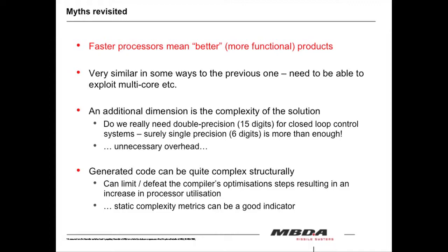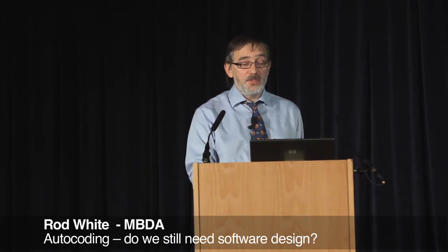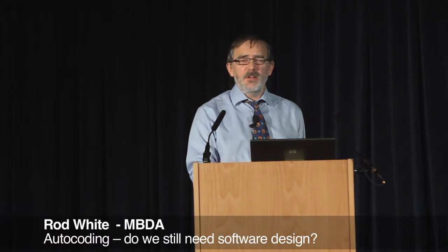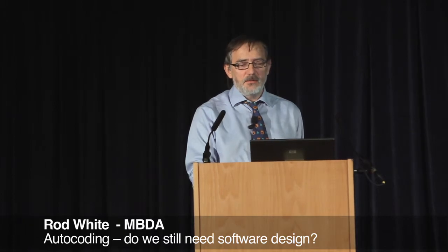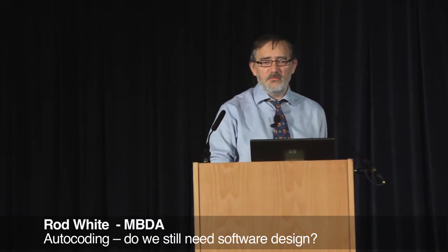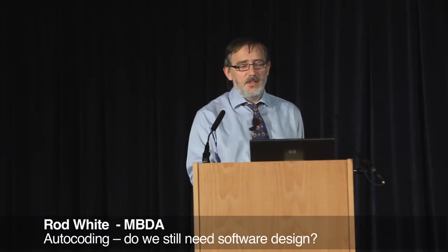Another myth: we might introduce more accuracy and complexity into the solution. Well, complexity for its own sake is not really worth doing. Accuracy, maybe we do gain something with higher precision floating point. But actually, if you're in a closed-loop control system where you've got 12 to 16 bits of input data validity, going to a 48-bit floating point value, what does it gain you? Not a lot. It's completely unnecessary.